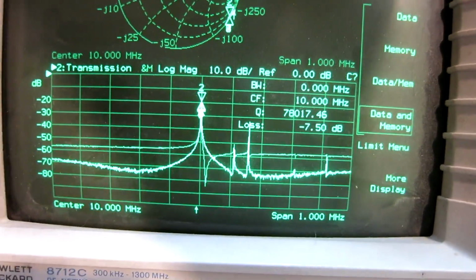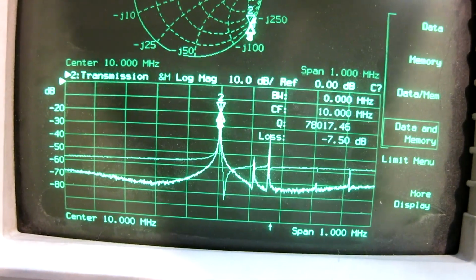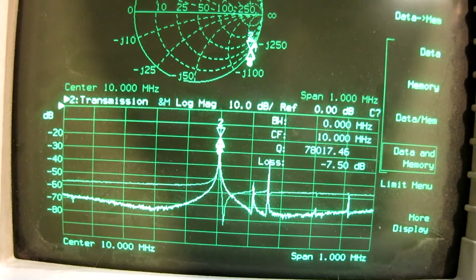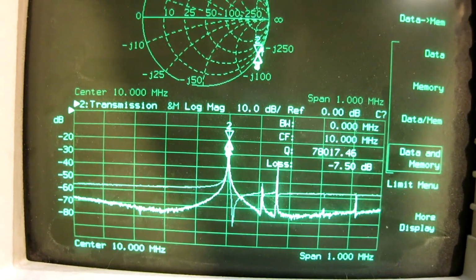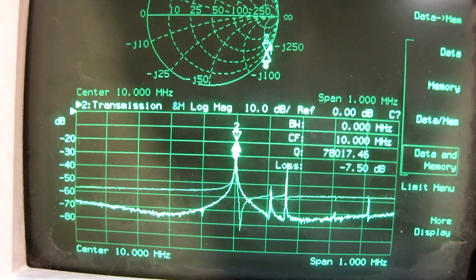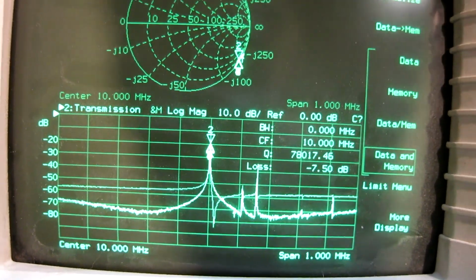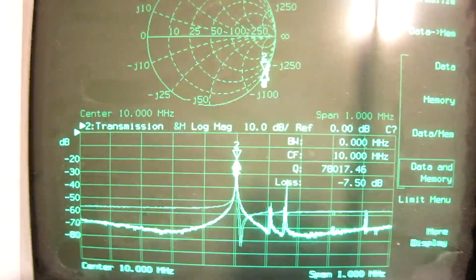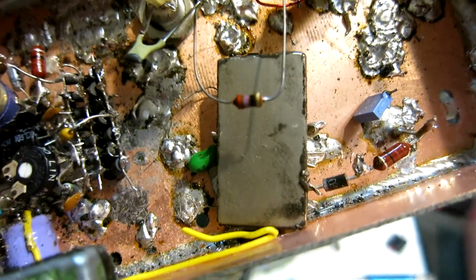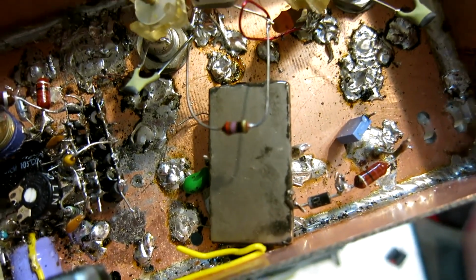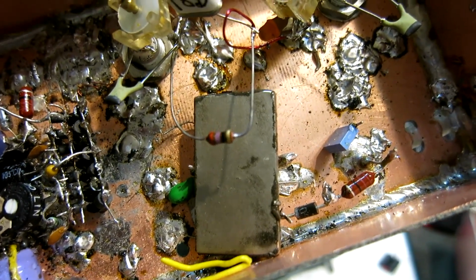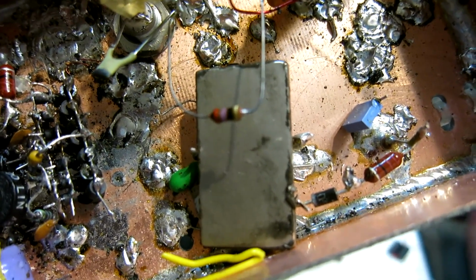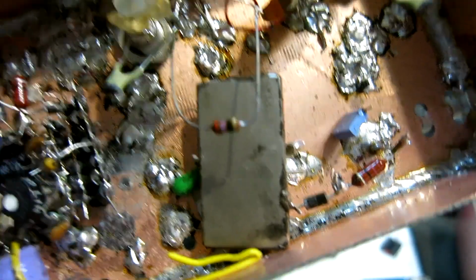Anyway, this is an interesting thing, so I can combine this filter with the other filter, because I want the very high impedance for the field effect transistors. But wanting two filters in series, nothing prevents me from using a series resonance for the first filter. The inductor is 27 microhenries, and I have tuned it by placing it near a magnet. I will remove the magnet while looking at the spectrum analyzer, at the network analyzer.